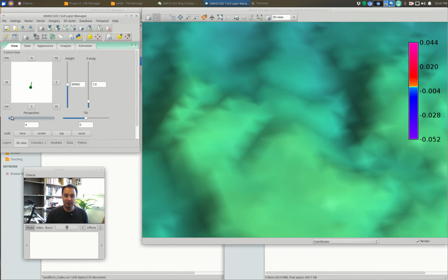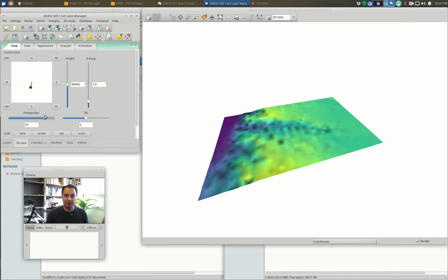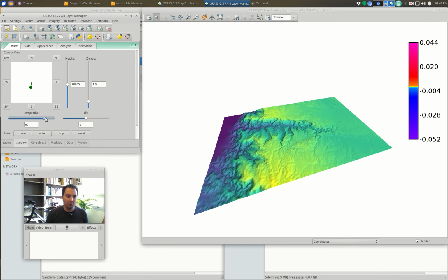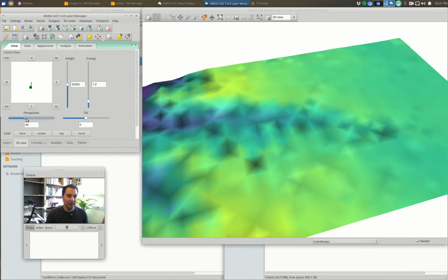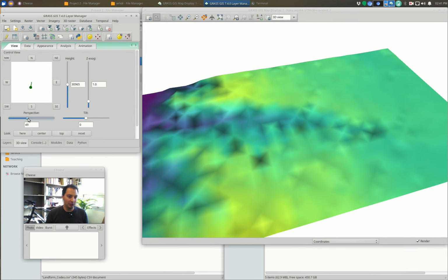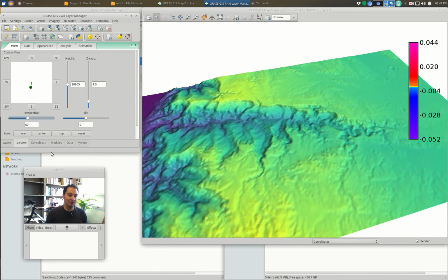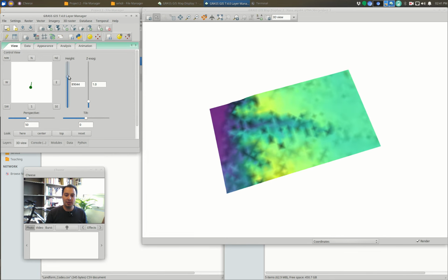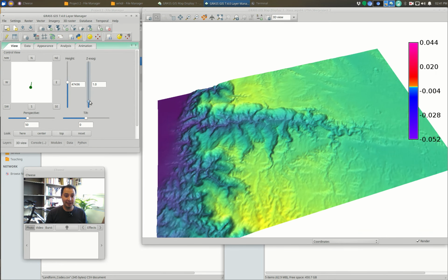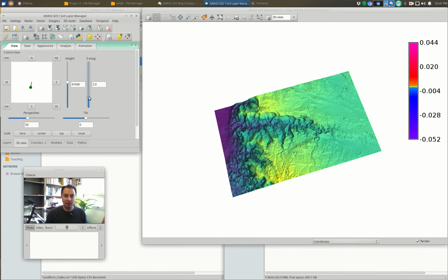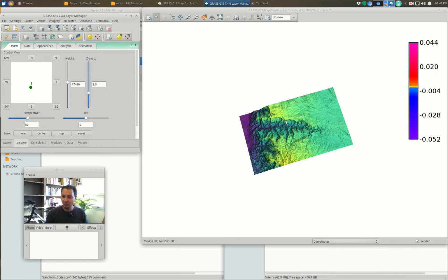The further you zoom in, the more distorted it gets. The further you zoom out, the more normal the view. And it tells you right here, this is essentially like the millimeter view. So if you want what they call a normal view, just put it somewhere at 50. It's like using a 50 millimeter lens, more or less, okay? You can change your height above the ground by sliding this. And over here we have, again, Z exaggeration. So again, if you do this, it's going to make it zoom away because you're multiplying all your factors in there by, in this case, 3, right?